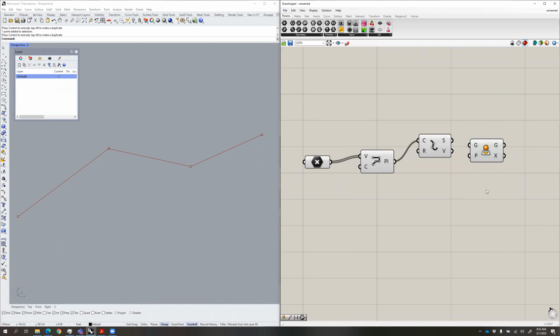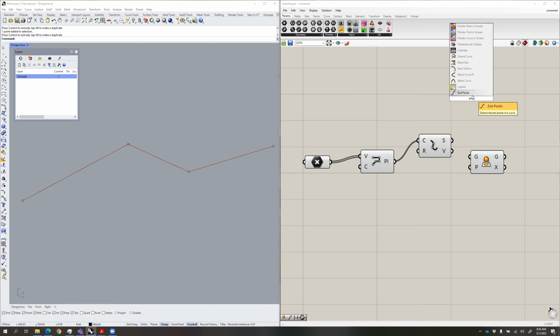The reason we want this tool is that, in order to get the horizontal length of each of these curves, we just need to take the curve and project it so it's flat. Then you basically get the horizontal length of it. That's the easiest way, because the horizontal length is not the length of the curve; it's the length of it in top-down 2D space. So what we're going to do is take each segment here and extract the endpoints. Remember, endpoints of each of the segments.